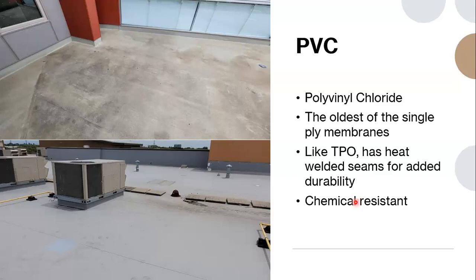It is something that we see from time to time, both on commercial spaces, or not really on commercial spaces, but on unit balconies. Again, in our experience, we're dealing with a lot of leaks with single ply membranes and punctures that happen quite easily. So it's not something that we would recommend necessarily over a residential space. One of the upsides to PVC over something like TPO is that it does offer more chemical resistance. So we do see it a lot more often on industrial spaces.